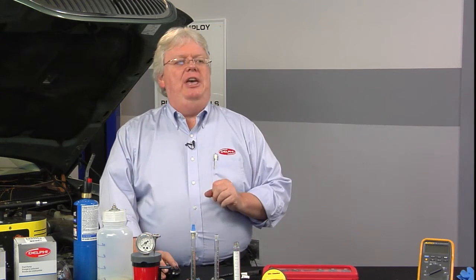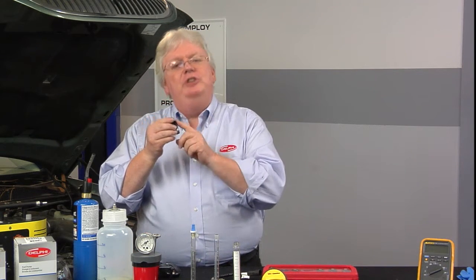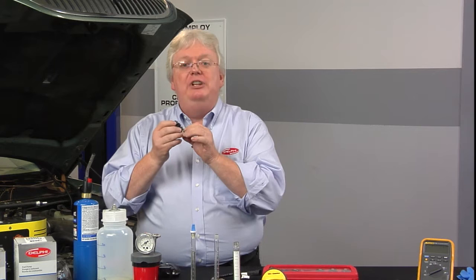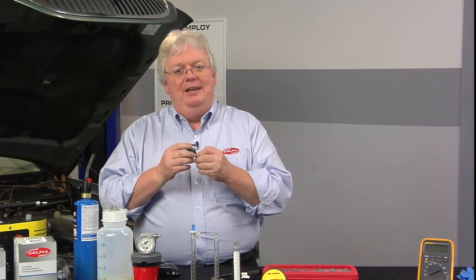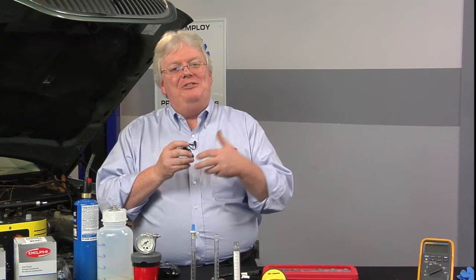So consider those things. Also, speaking of injectors not firing, late model fuel injectors will be shut off if there's an ignition or any other reason for a misfire, and that's only going to affect things if you were measuring with a gas analyzer in the tailpipe.